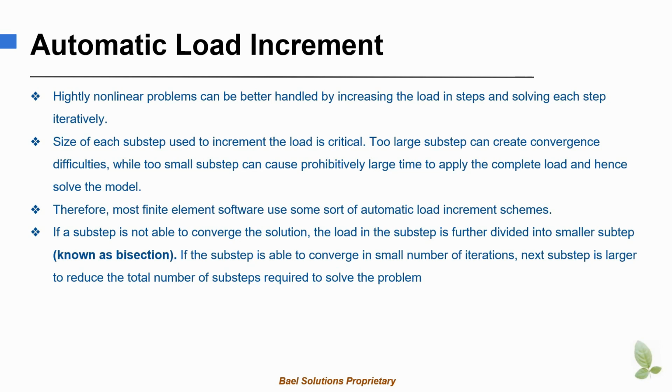Normally, the incremental load in the substep is divided in half in one bisection. Thus the load is applied in a large number of small increments for highly nonlinear models, while a small number of large increments are used in moderately nonlinear models.